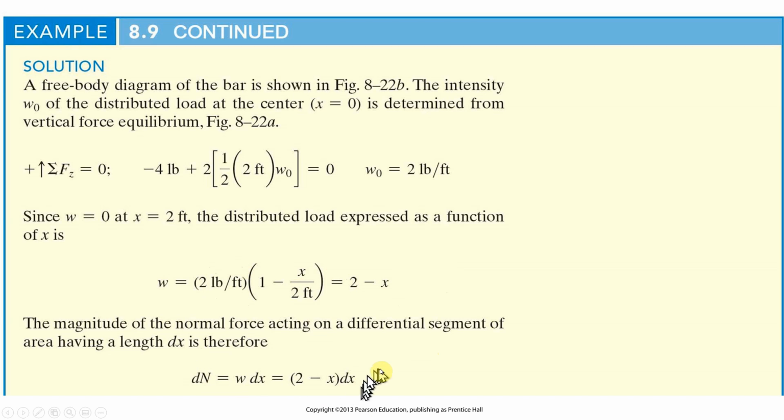The differential. So we still have to do an integral from 0 to r. And so we want to know at a distance of r from the center, what is going to be the normal force? Well, it's going to be W dx or dr, whichever you prefer. So now it's starting to look simpler, something we can handle.